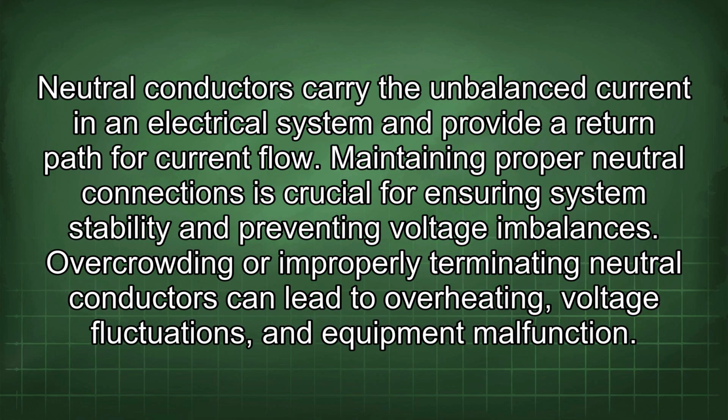Neutral conductors carry the unbalanced current in an electrical system and provide a return path for current flow. Maintaining proper neutral connections is crucial for ensuring system stability and preventing voltage imbalances. Overcrowding or improperly terminating neutral conductors can lead to overheating, voltage fluctuations, and equipment malfunction.